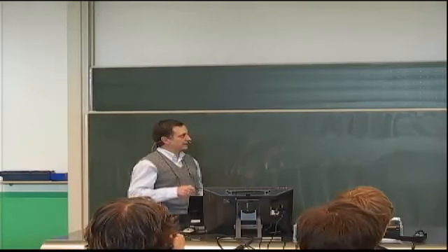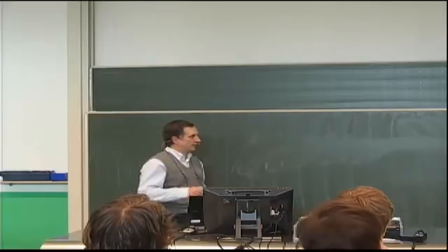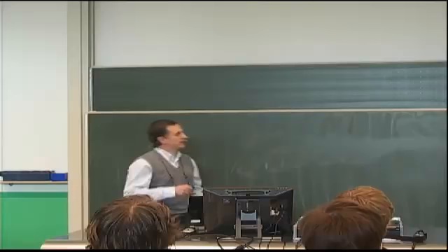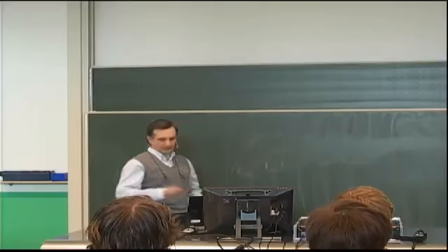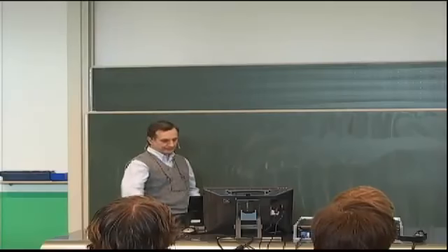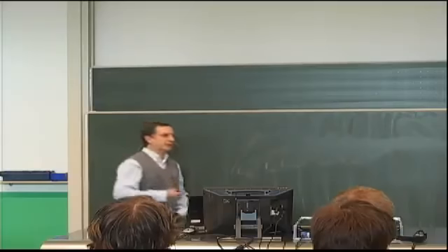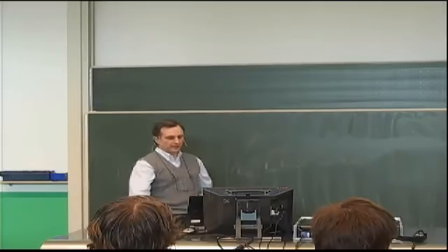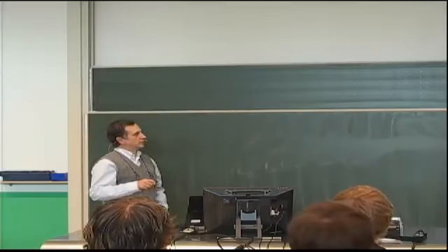If you look at the sigma y on this edge and on this edge, you will see it's 0. And if you check on tau xy on all edges, you will see it's 0. But we had not satisfied the conditions related to sigma x, which would allow us to determine finally k0 and an. And k0, again, from Fourier cosine series theory or from simple integration, is the average stress. Basically, if I integrate with respect to y